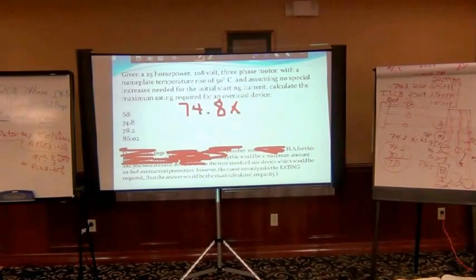125%? Oh, no, 1.15. Why is it 1.15 instead of 1.25? Because 50 degrees Celsius is more than 40 degrees Celsius. That's right. The second row there, which I neglected to say anything about, is a 40 degrees Celsius or less value.